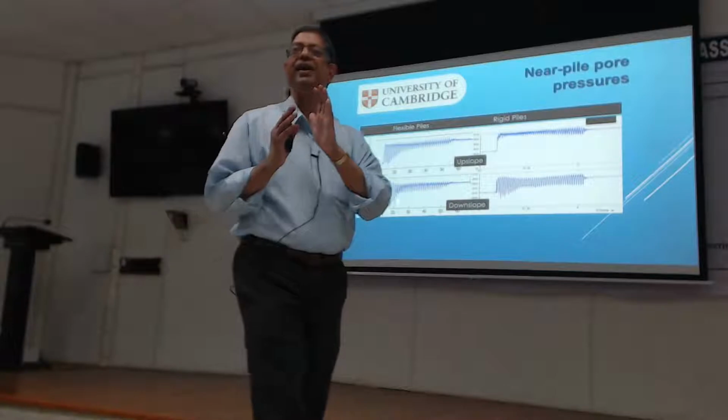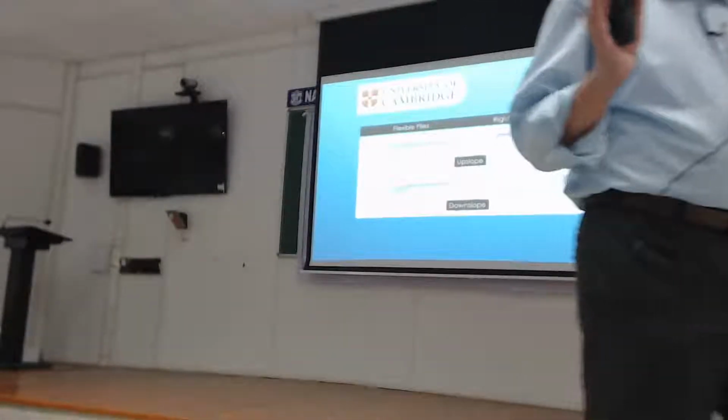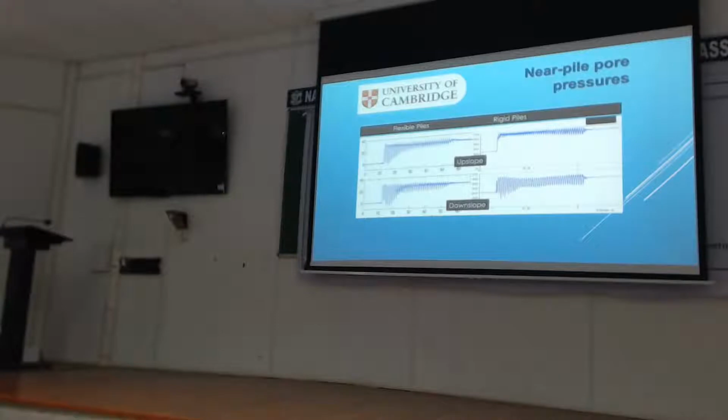So something is happening downslope of the pile, which is quite important, which nobody would think of. Because you'd expect, okay, if the piles are here and the slope is moving this way, I'm always focused on this part because I'm thinking, oh, my soil is coming towards my pile. It's all going to be mobilizing lots of passive pressure, but you won't worry about the other side of the pile. Well, that soil can just flow away. Who cares, right? But according to this, no, you need to pay more attention to that soil.